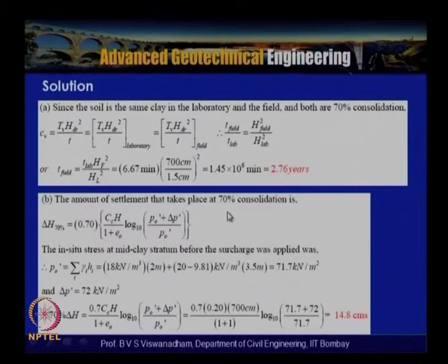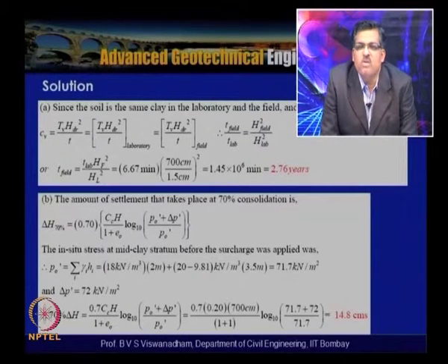Now, the solution works out like this. Since the soil is the same clay in the laboratory and in the field, and both are actually at 70% consolidation, the coefficient of consolidation will be the same. So, time factor Tv is equal to Tcv by H square.